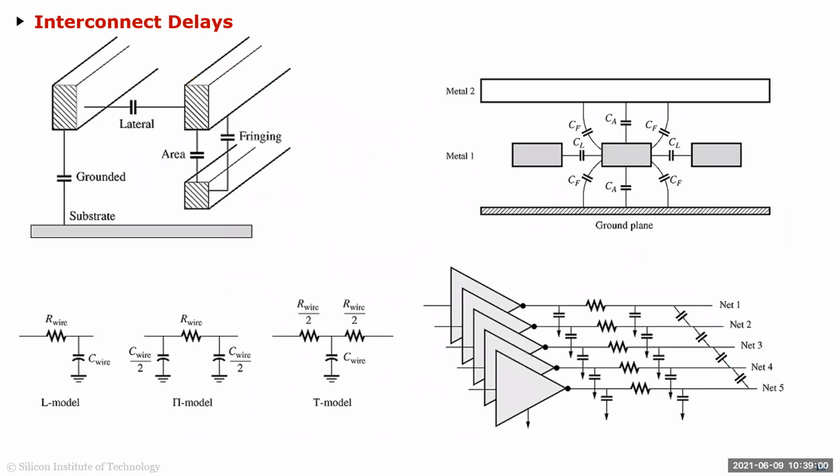Okay, and then for interconnect, in these derivations, for both the logical effort and for path delay, we're not going to consider the interconnect because that is layout dependent. So that is actually done post design. This delay optimization and all that is done pre-layout. So you don't have this information, but I just wanted to show that this is also part of the delays.